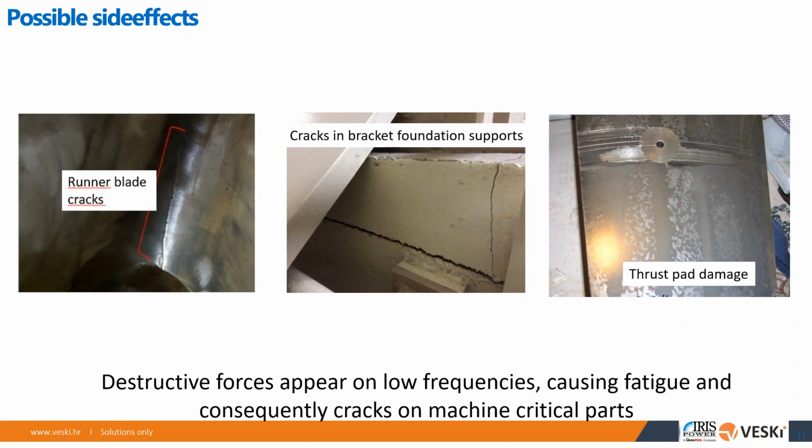So in this particular case, if you just had an overall number measured, it would be like 0.5 millimeters or 1.23 millimeters per second, which is not really so high, but when you turn it to displacement, it becomes a movement of 1.3 to 1.6 millimeters peak to peak.